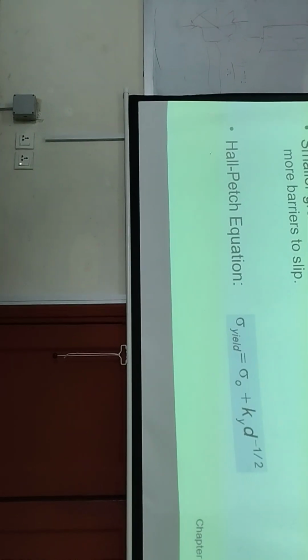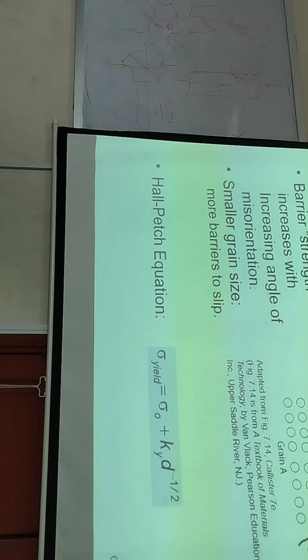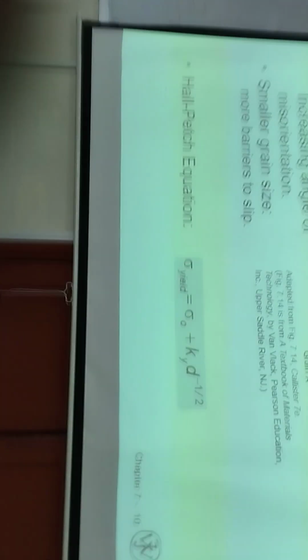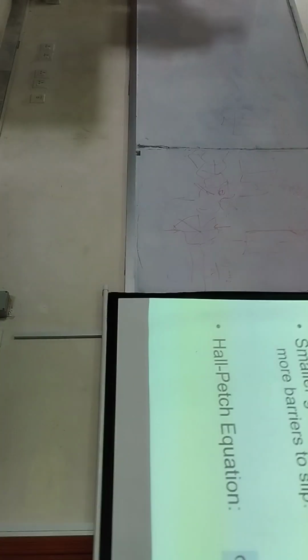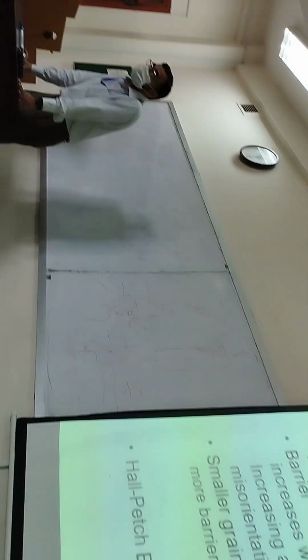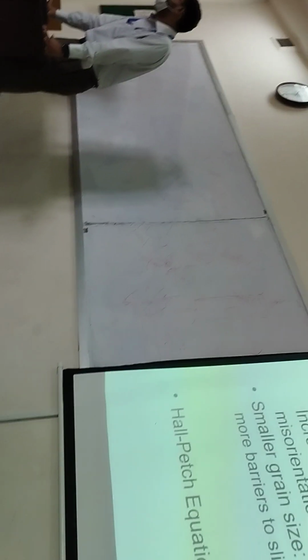I could ask you what kind of strategy can you apply onto your sample in order to increase the strength of that material. First of all, you have the idea that if we reduce the grain size, we are going to strengthen the material. Sometimes people have the misconception that if we have a single crystal sample, it is going to increase the strength. That is not true.